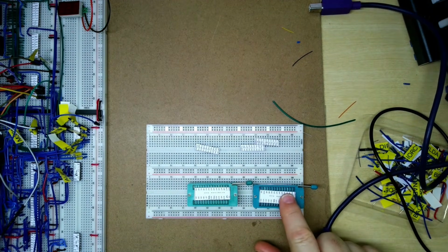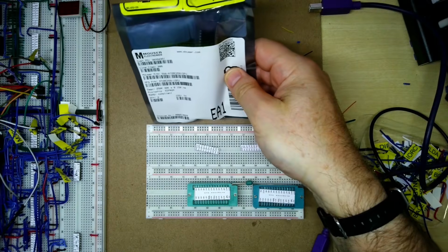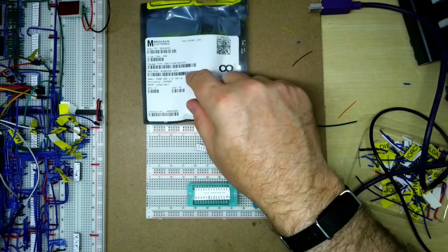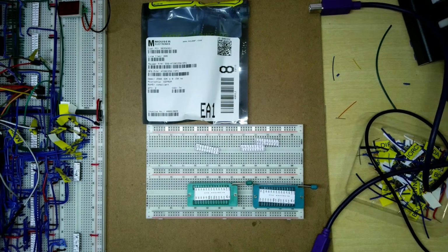We've got the two zero insertion force sockets. I've got the two 32K EEPROMs. These are 32K times 8 bits, 150 nanoseconds. So they're probably faster than the EEPROMs that existed at the time of the DeskPro, in that EEPROMs around that time would probably be about 250 to 450 nanoseconds access time. But compared to our RAM, which has 55 nanosecond access time, these are probably a third of the speed of the RAM. So we should certainly see some speed up in performance if we actually shadow the EEPROMs into RAM.